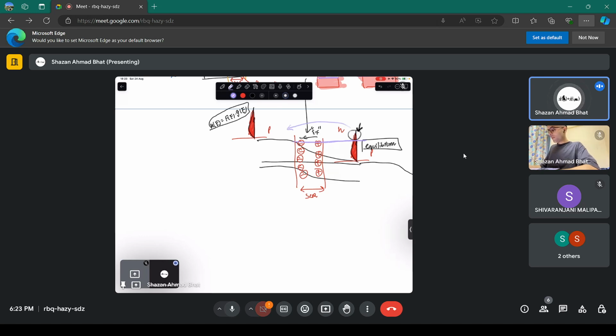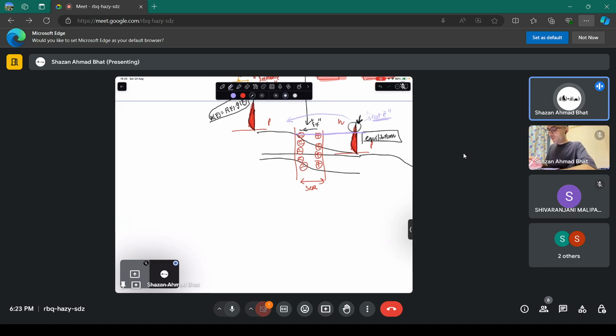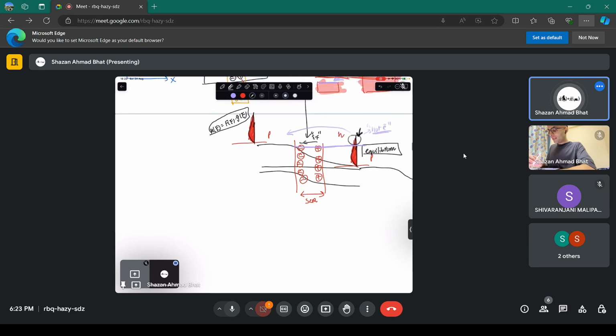The only way to stop them is to reduce the barrier more and increase the barrier on the other side. But these are something called hot electrons or Fermi electrons. This is something called the Fermi tail. They are always there to go to the other side. So what happens now when we apply the voltage? Now we know that this is the distribution of electrons on this side, this is the distribution of electrons on the other side. But very few electrons are here which can normally go on the other side, and they don't constitute a significant part of the current.